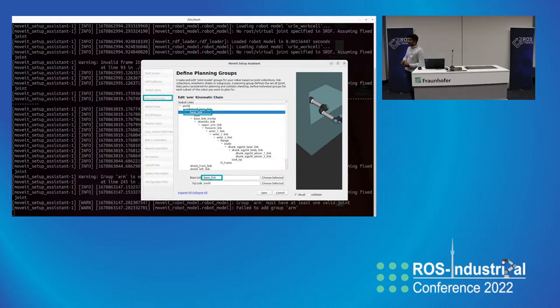If you wanted to add one more robot near to that, I think in order to do that, you can define it in the URDF itself, that you have two robots separated by this distance, and that's the world. So you export it, and then you create different planning groups, one for each robot. Say that you have one robot for the left part; you say arm left, and then you have arm right, and that's how you define the planning groups. Did I answer you? Yeah.